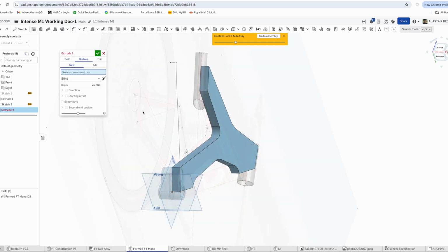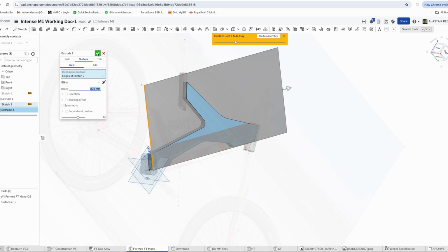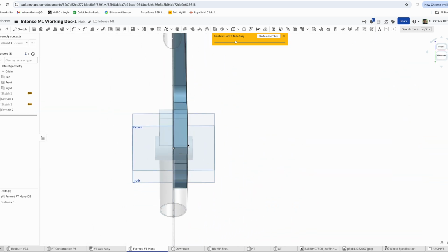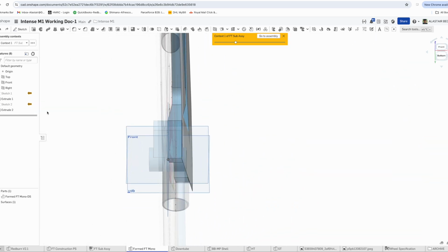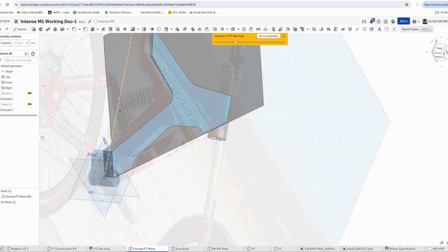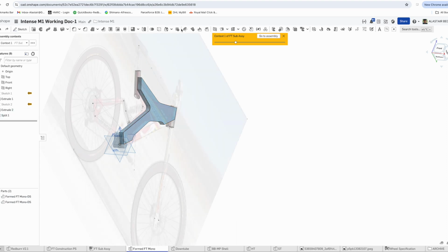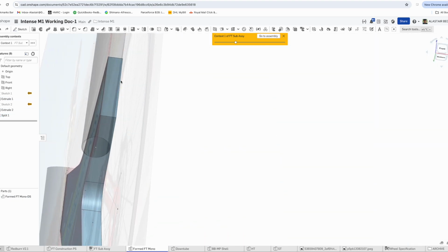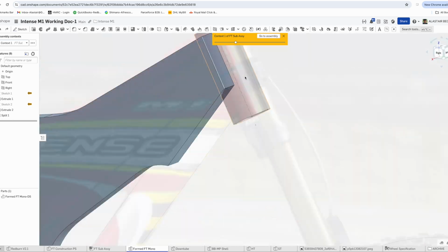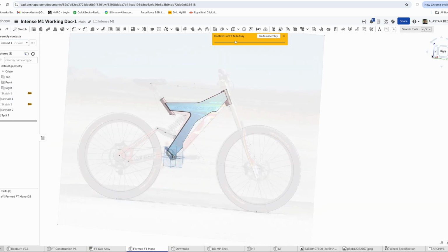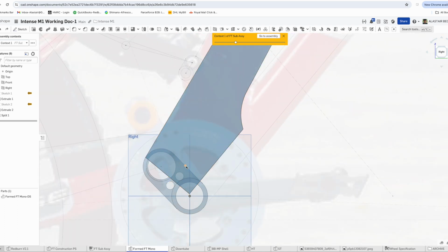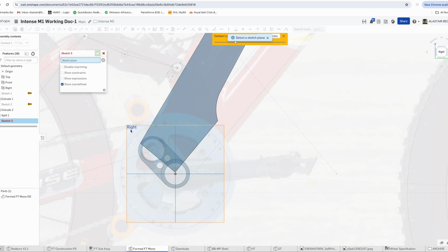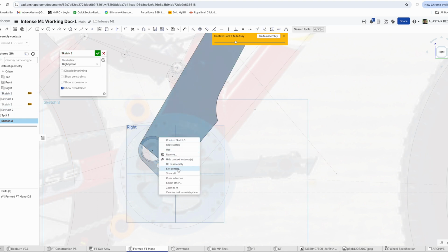So we're constraining that, and then we're going to extrude the surface the full length, and obviously we want it to completely cover the whole part that's been extruded, and you can see here. We're just going to tweak that, and then split the solid with the surface and remove the outer shell. It doesn't really look any different visually, but you'll see now that it's a lot closer to the seat tube diameter without really affecting the head tube and bottom bracket section. So we'll get a much nicer interface for where welds would go if this was being turned into a production part.